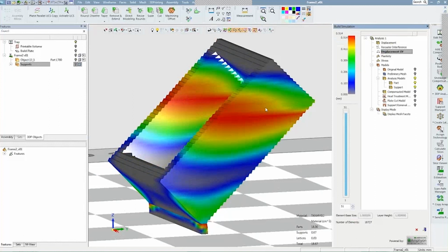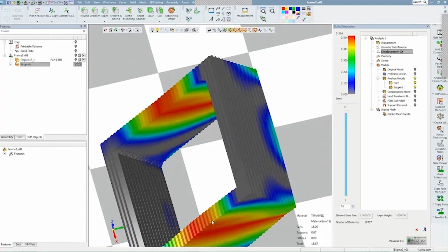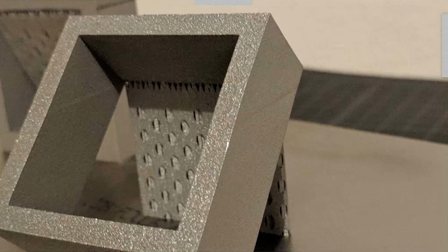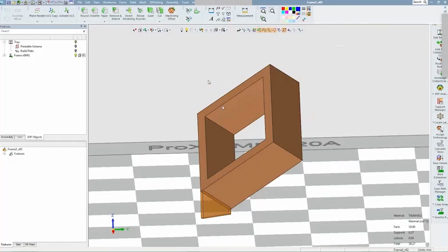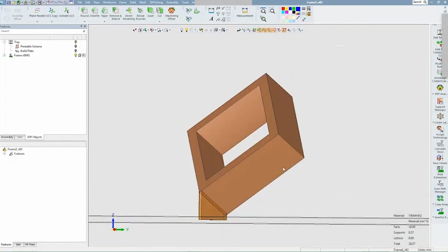And this is one of the unintuitive things there, is that that top red section in the top left is actually coming after we connect, and it's because of that angle and dissimilar cross-section where that material on top is pulling it inwards. So you can see our part, we have that distinct shrink line where they come together. And at about 200 microns, 300 microns, you would still expect to be able to see that with your eye. So we're going to try to reduce that amount of material a little bit more.